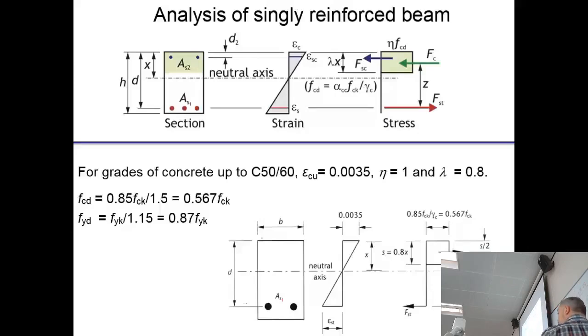If the concrete can't cope with the compression, you can put steel in the top to cope with it. It's got the same stress value whether it's in tension or in compression. Your concrete is only about 35 to 50 newtons per millimetre squared. Again, if your concrete starts failing, your steel has 435. But you try not to put steel in because steel's expensive.